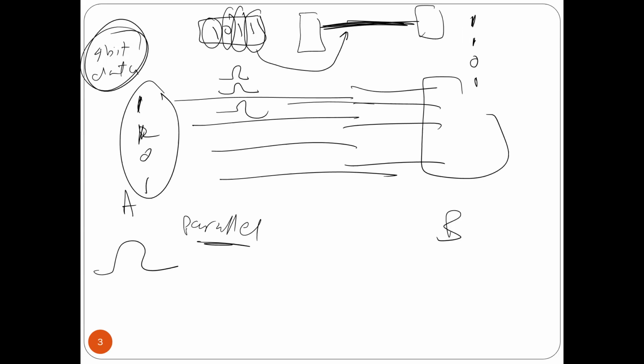It's very easy to observe that this one is just slow because you're going to transmit bit by bit. But here I transmit 4 by 4. So anyway, this one is slow. This one is fast. However, the good thing about this one, we need only 1 wire. You get what I'm saying? And it is used when you learn something like I2C or microcontroller, things like that. You will see this one is used. USB, by the way, is serial. So it is used, and this is the most important thing.